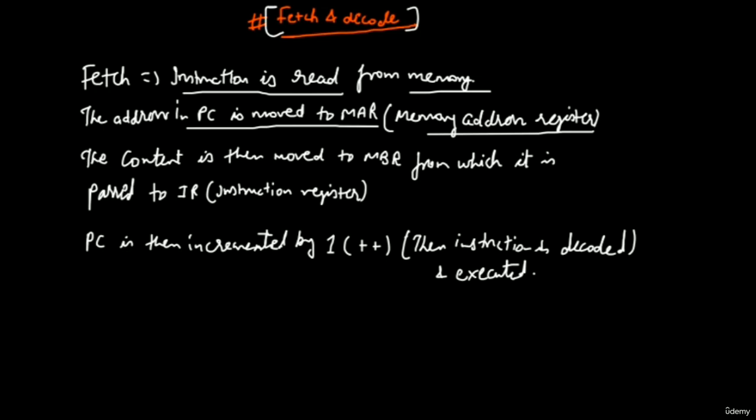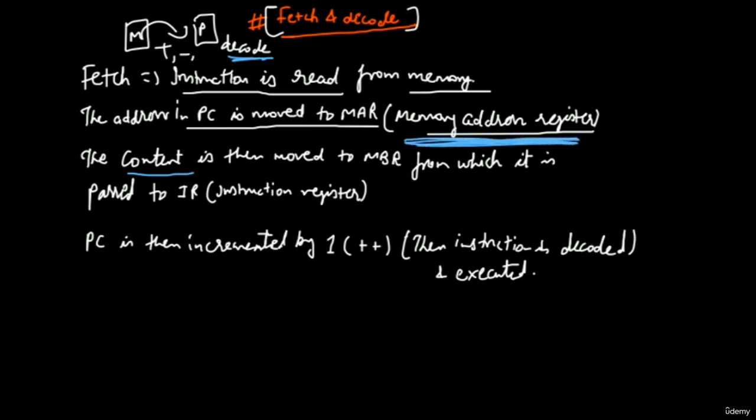First of all, fetch means taking the data from the memory and loading it into the processor. Now, the processor has to decode. Like if I say to add, subtract, multiply or divide, it first has to understand what it needs to do. For that, it has to decode. After decoding the content, it gets the data from memory, and the instruction register holds what to do, add, subtract, multiply, divide, whatever, and then it increments. Why does it increment?